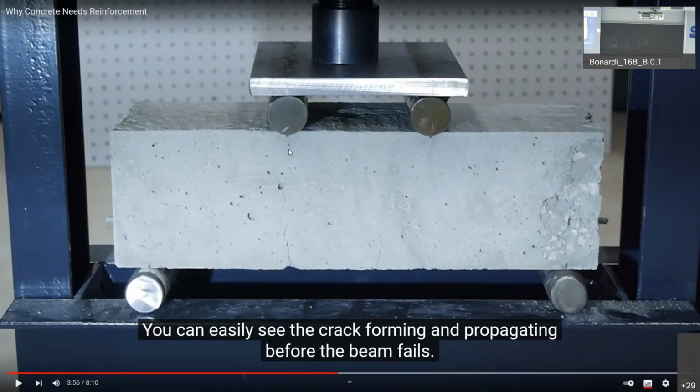From this part to the bottom, there is a crack, so basically there is no exchange of stress between this part of the structure and this part of the structure. So the concrete is ineffective here, but there is the metallic rebar that we can see here and that we can imagine here. This rebar is providing the same tensile force that is provided by the compression in this part.